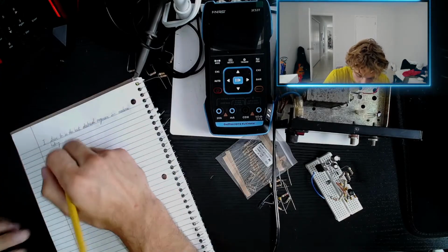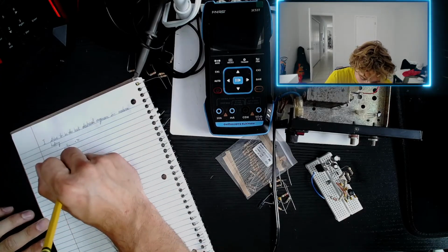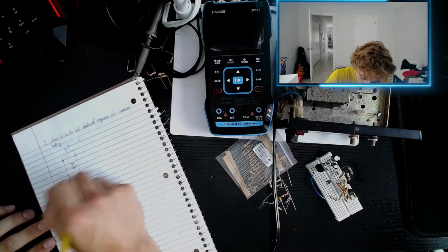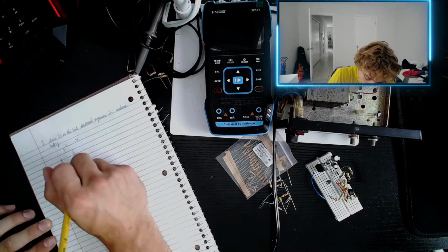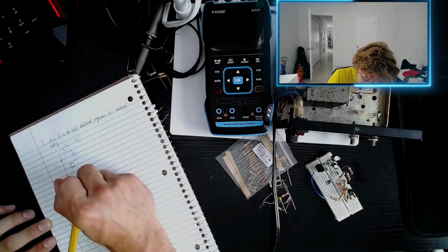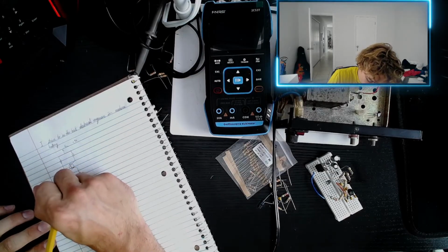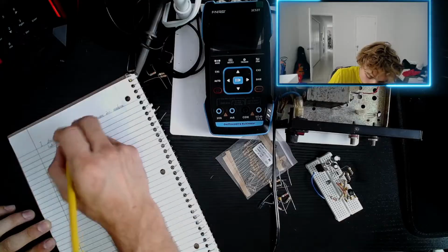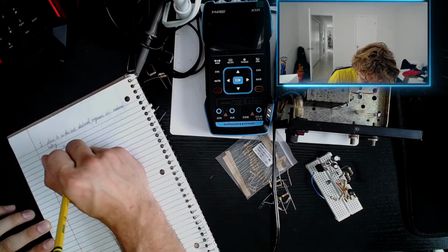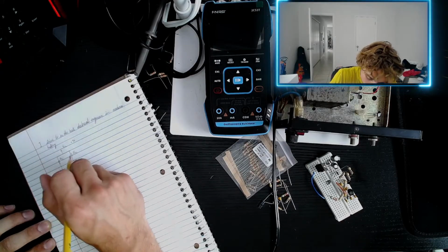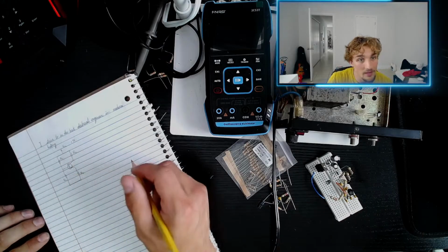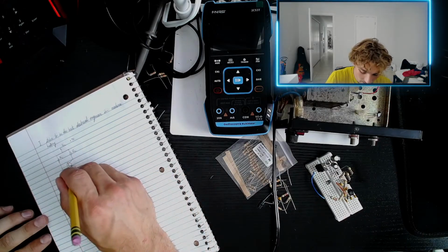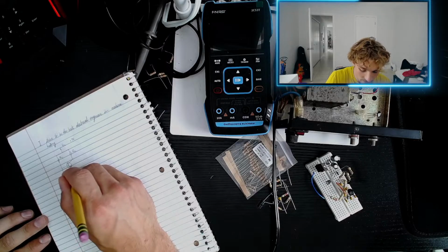Nine volts. So we're going to want to label everything. Okay, these two are grounded here. This is going to be our emitter resistor, RE. We'll consider this R2, R1, and RC, right? This is the collector. This is the configuration of the NPN BJT, where we're going to have an output here. Our arrow is facing this way.